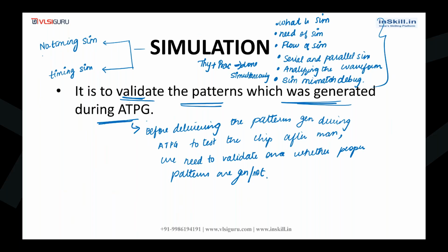In our DFT course, as of now, no timing simulation is covered. Timing simulation is not covered, because to do timing simulation we require an SDF file, which is not available in our institute.